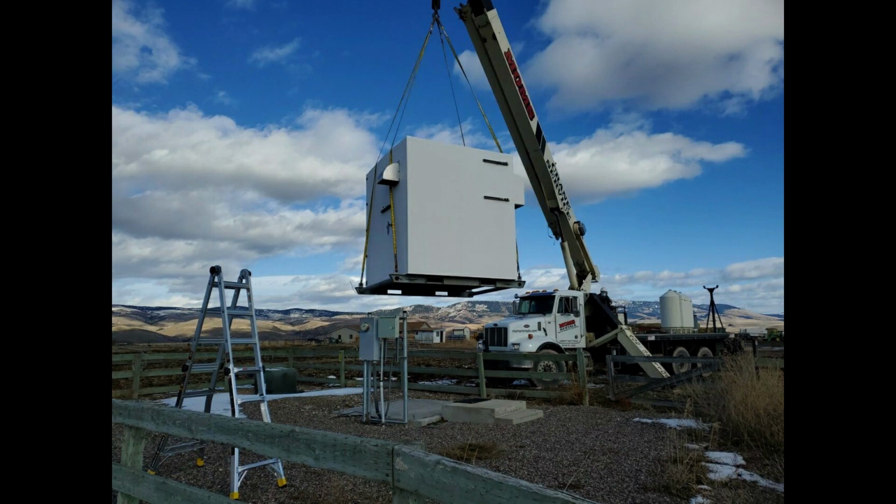After the clearance void time, your reserved space within the IFR system is released for other traffic. There are several other ways to receive a clearance at a non-towered airport. If you can contact the FSS or ATC on the radio, you can request your departure clearance. However, these frequencies are typically congested, and they may not be able to provide you with a clearance via the radio. You also can use a remote communications outlet, RCO, to contact a FSS if one is located nearby.